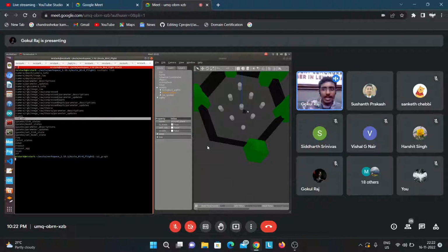That is how it works in a real robot. Basically, the robot runs subscriber code, subscribing to cmd_vel, and based on the velocity, it's publishing the PWM values. That is what you're simulating over here. Understood?